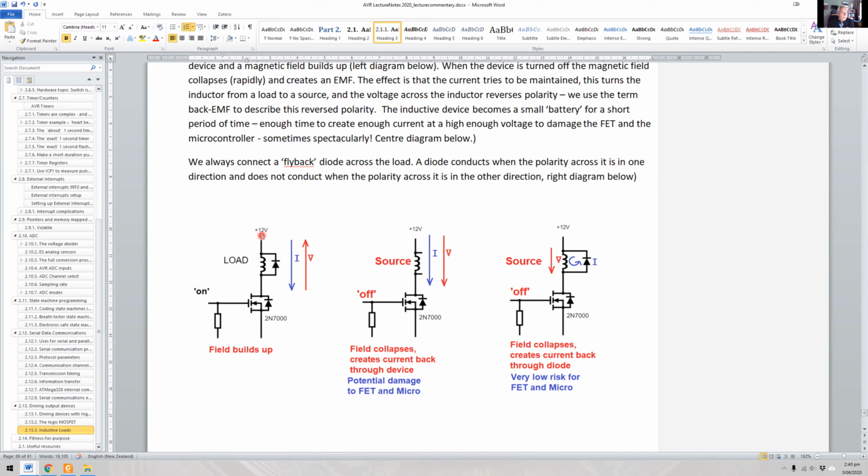The conduction is okay. Now you'll notice that I put a diode here, and there's a built-in diode here as well as a side effect of its manufacturing process. This diode will not be conducting. Diodes conduct in the other direction. So this diode is here to conduct if the voltage ever swaps.